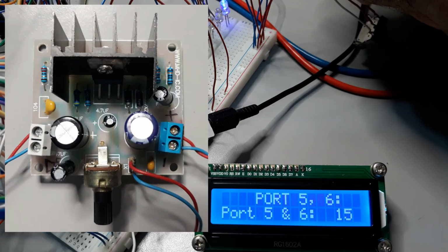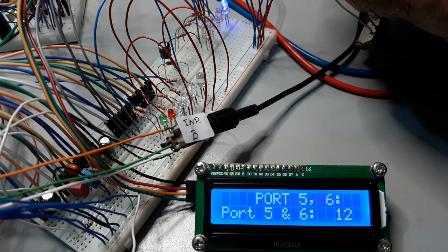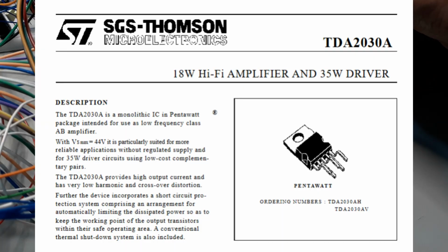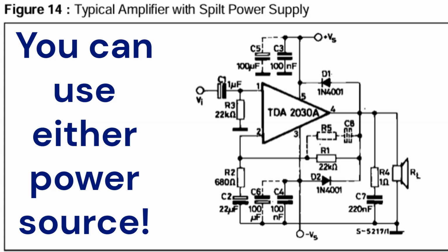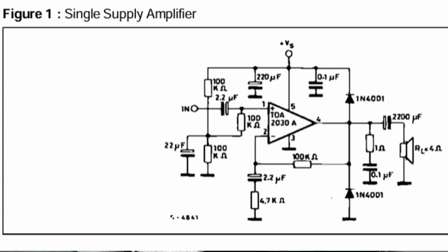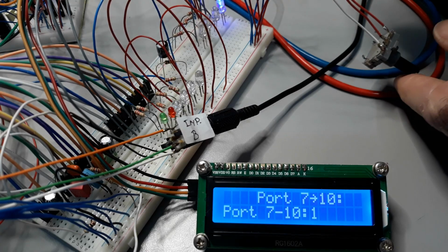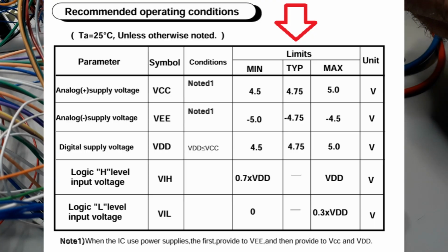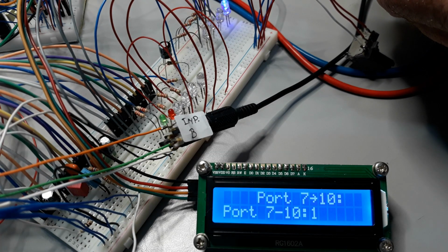To keep everything at a low level, 2 independent power amplifiers were used, both based on the TDA2030. Care was taken to power these amplifiers using a symmetrical supply. The M62445 itself is also powered using a symmetrical supply, providing plus 4.75 volts and minus 4.75 volts direct current.